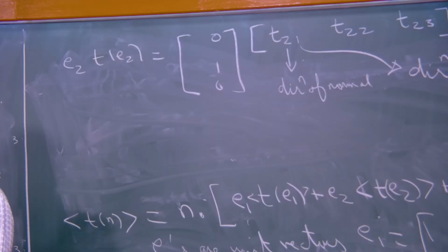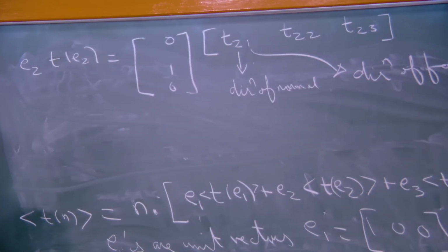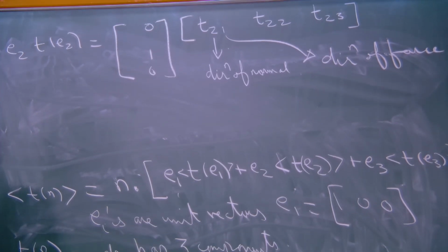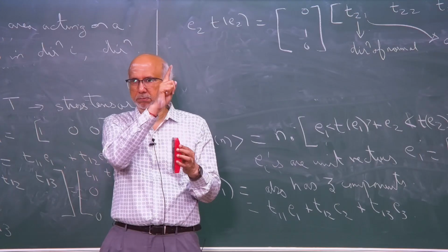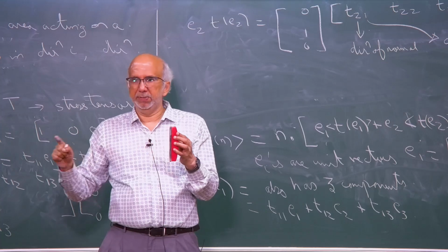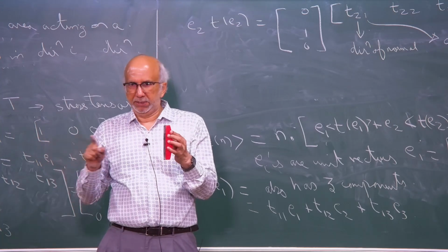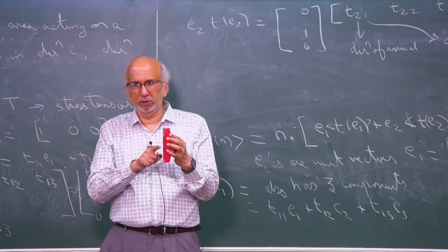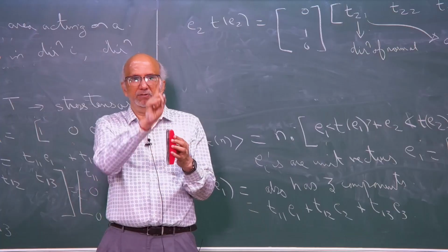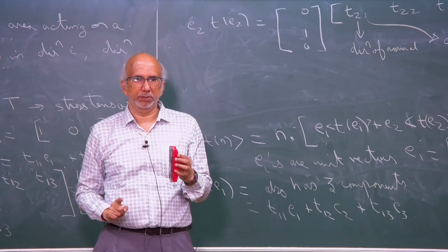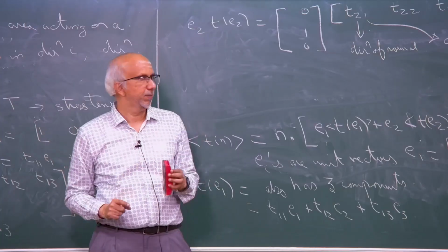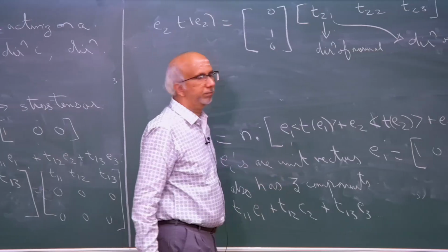So, on this surface, the first subscript is this, but on this surface I can have all three components of the force. I will have a force in this direction, force in this direction, force in this direction, 1, 2 and 3. So, the first subscript tells me T1, T11 will be the normal component, T12 will be a tangential component, T13 will be the other tangential component. So, on this surface there is one normal direction, two tangential directions. That is basically what I am trying to write here.